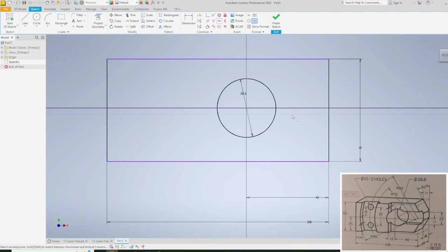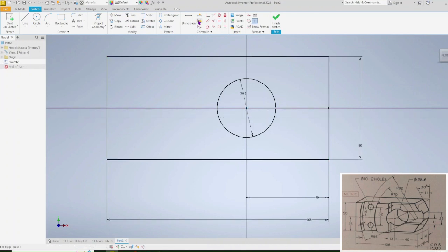I'm going to go ahead and add some lines like this because I do have some angles that need to be taken care of. So I over exaggerated these lines, and I'm just going to use my coincident constraint to lock in with this center point here. I also want to make these two lines equal with each other.